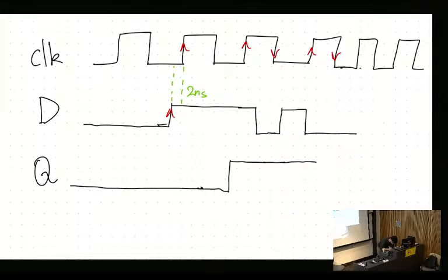Okay, so this is good though. We're going through a timing diagram, and let's say the output goes, so now it's low. Will it clock on this edge signal? Yep, it probably will. Good, so the output stays low. It clocks on this edge signal here, so it goes low. And then let's imagine the input signal does this. I'll just line it up. So it goes high at this point here, and it goes low there.